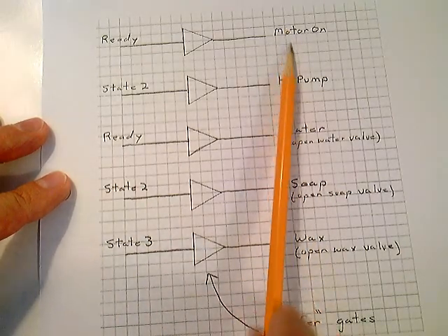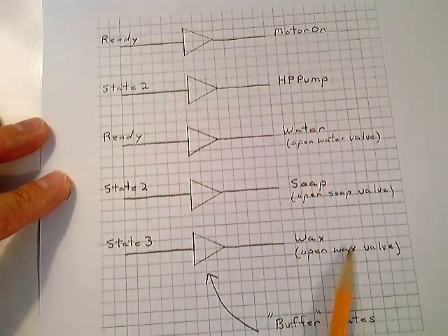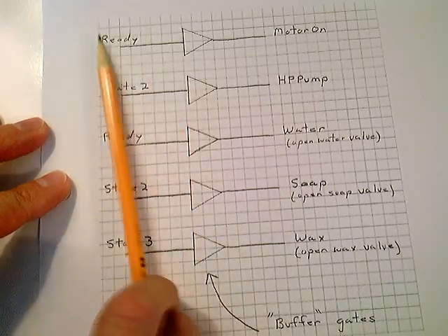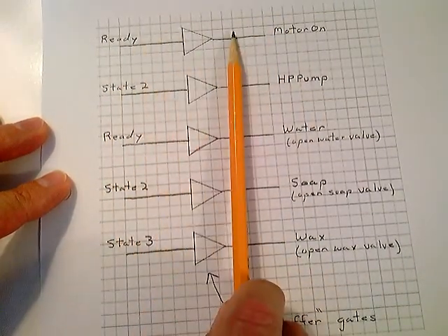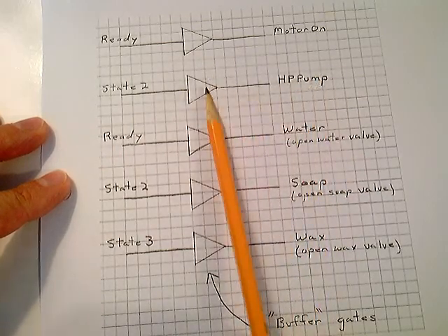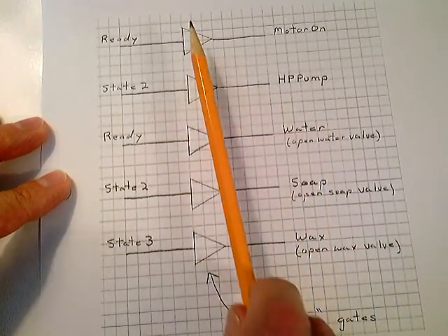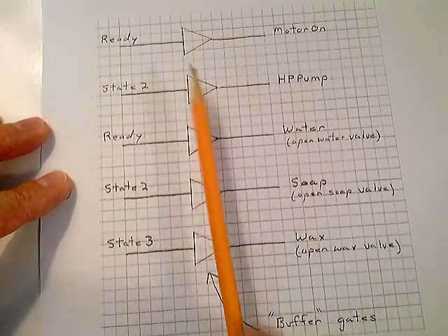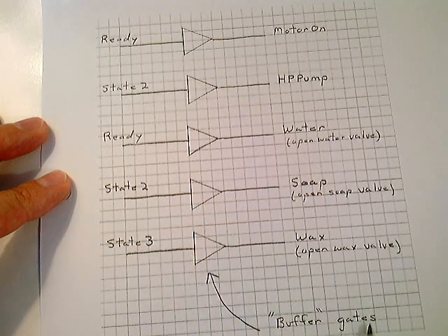And these out here, if something happens to the circuitry out here, you don't want to affect it in your control. So we put these buffers in as isolators. They just isolate the circuit. If this goes to a 1, this goes to a 1. If this goes to a 1, this goes to a 1. But if something happens out here, it'll take out this output circuit, which is very inexpensive. It won't get to your control. So that's why we buffer. Engineers put these buffer circuits in, these buffer gates, to just isolate. We talked about that before. And that concludes the lectures on synchronous logic design.